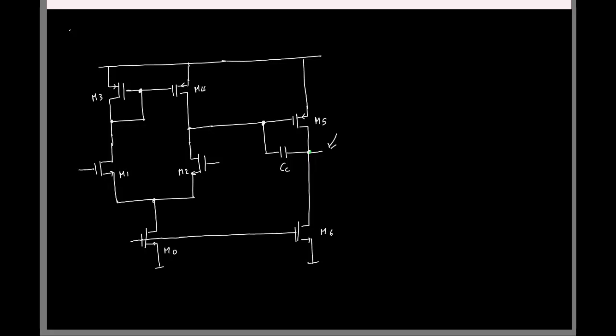So this op amp, where are we going to use this op amp finally? In negative feedback. Okay, so remember, let's say you have a unity feedback. We'll put it like this, right? And this one I'll actually have to connect a bias voltage VCM, which means this will also be at VCM and the output will be at VCM. So what is setting the output common mode?